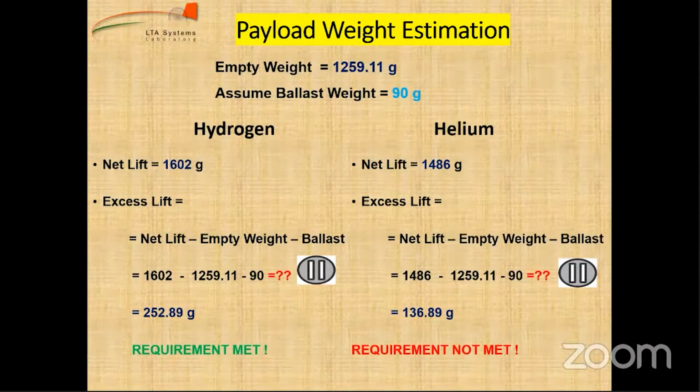Yes, sir. Thank you, sir. But yes, like in every design, you need to have a robust design by keeping margins. So by experience, you come to know how much variability to expect, and that much margin. So my ballpark value is around 5%. Expect that what you will get is 5% heavier than what you plan and 5% lesser thrust, or motor will last 5% lesser watt hours. That way you will be able to get. But if you do it from a very reliable source, then the variability will be lower.